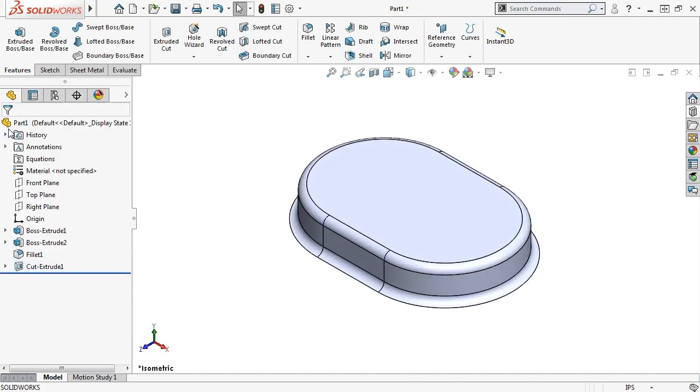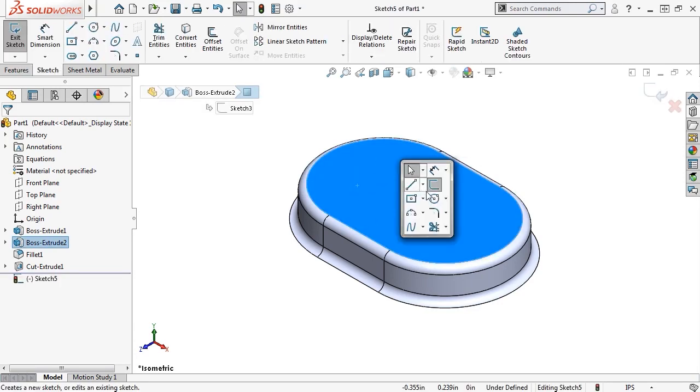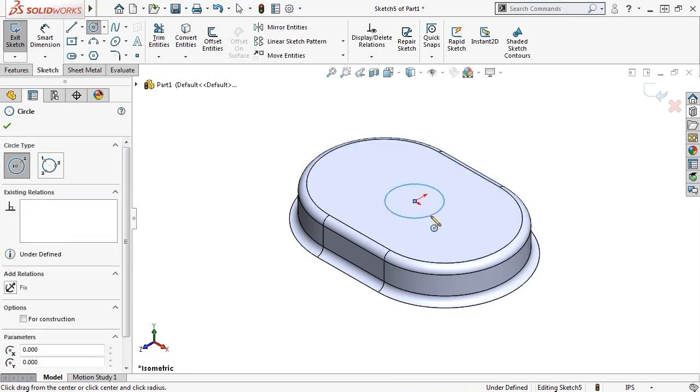In addition to stamping this shape into the sheet metal part, I also want this forming tool to create a round hole. In order to do this, I have to color a round face red. Unfortunately, I don't have a round face to color, so I'll have to create it. To create the round face, I'll have to use the Split Line feature. I'll start a sketch and create the shape I need. A simple circle.